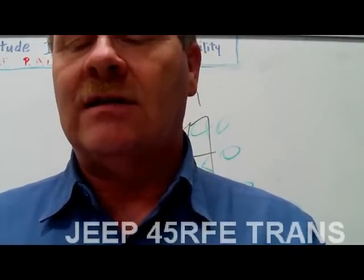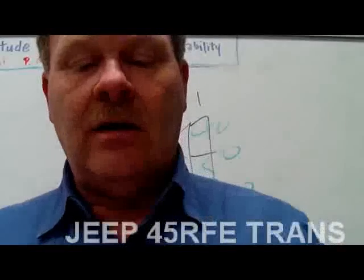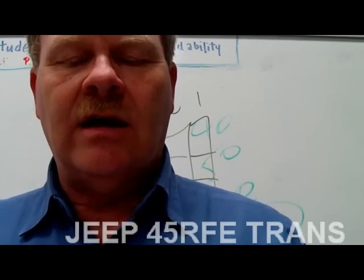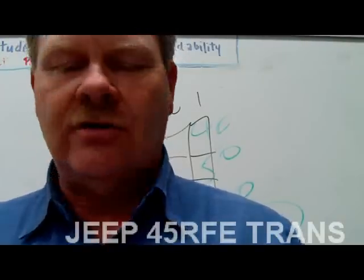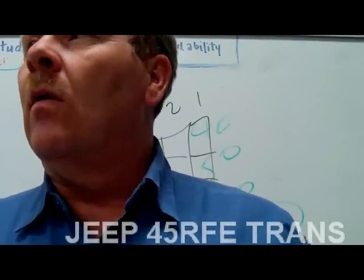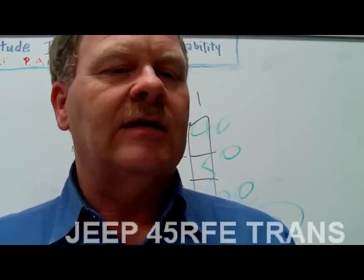The crank position sensor is a direct input, believe it or not, on that one. It also gets an engine RPM reading in addition to crank position. So you've got an indirect input to the TCM, manifold pressure, which is read from the MAP sensor. Remember the old modulator valve used to use that. What's manifold pressure telling us? Why does a transmission control module need to know manifold pressure? Can anybody tell us that?